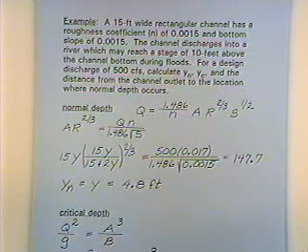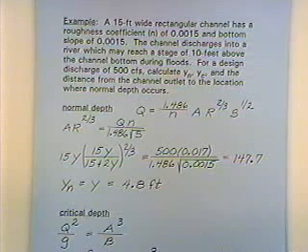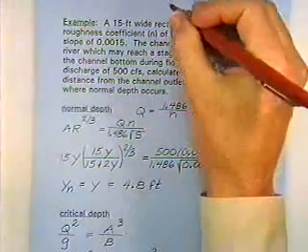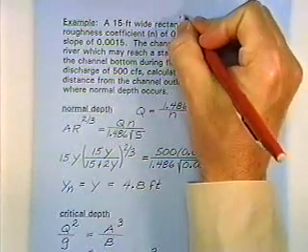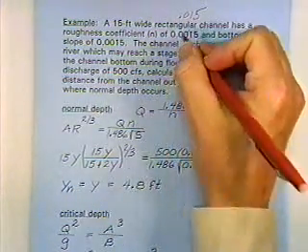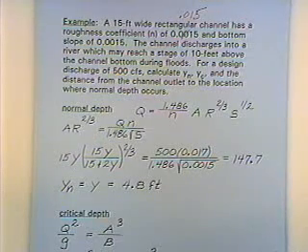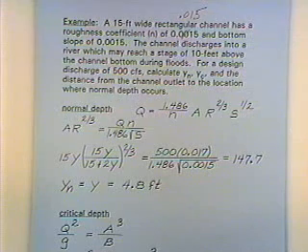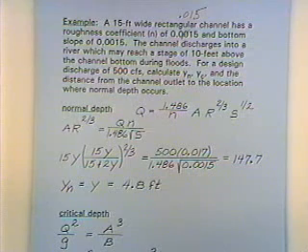Yeah, I found a typo. So that must mean that the channel bottom slope should be 0.015. I've got an extra 0 in there. Can you fix that in your notes? We've got to change the Manning's roughness coefficient to 0.015.